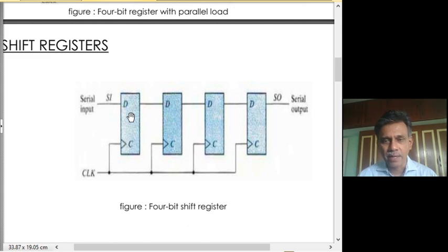The cross-coupled NAND gates are being encapsulated into a black box called D latch, and 2 such D latches are used in a master slave configuration, and we came up with a building block called the D flip-flop, edge triggered D flip-flop, and these are those units.